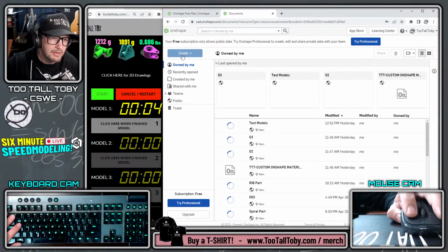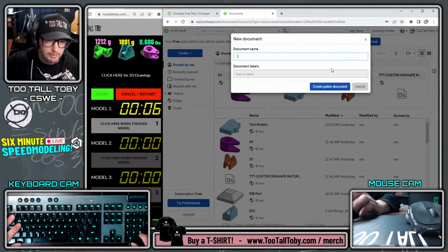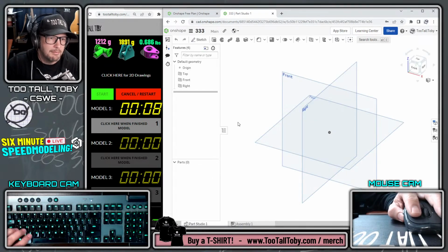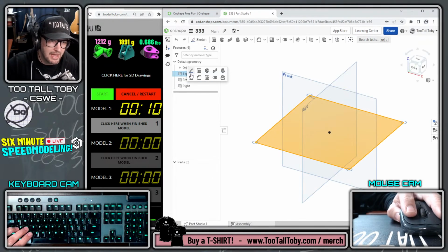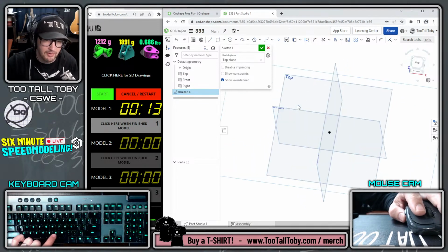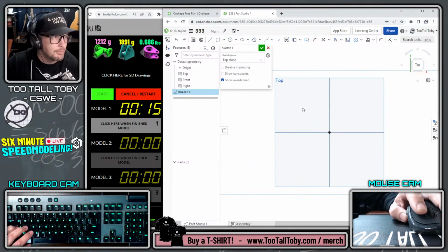So we're going to start a new document here. I'll call this 333 because it's the third model. And I'm going to go to the top plane, begin a sketch, and orient my view by pressing the letter N on my keyboard. You can see I've got my keyboard cam down here.